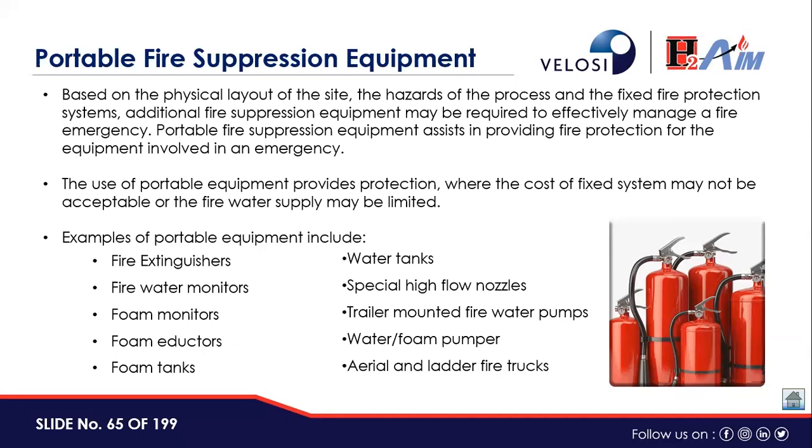Next question. How to optimize fire protection at instrumented safety system plants? See, the fire and gas detection system is a part of the firefighting system or fire prevention system, and the fire and gas detection system is designed in accordance with IEC 61508 and IEC 61511 requirements, and their reliability level and SIL level are maintained as per applicable SIL requirement.